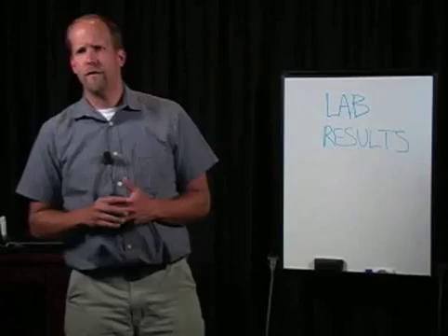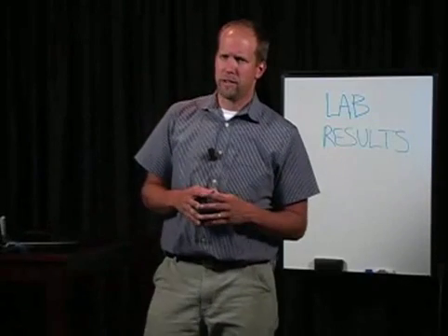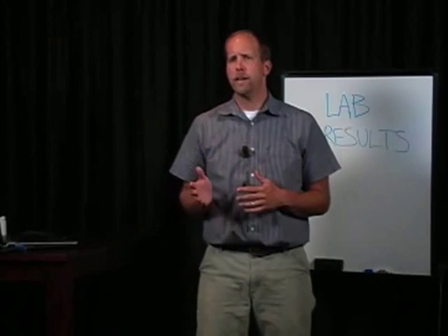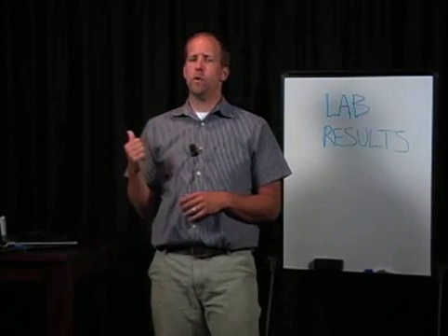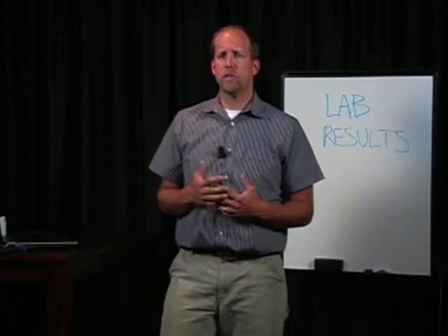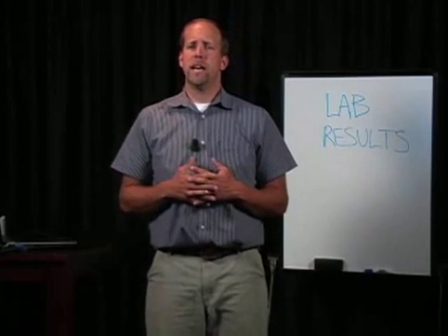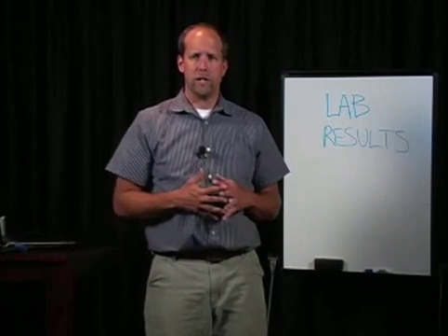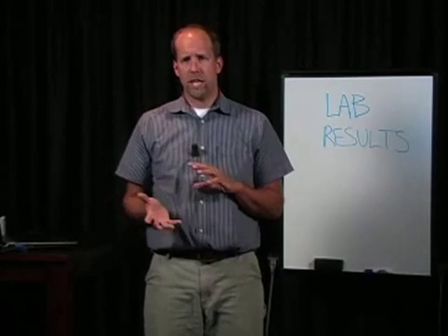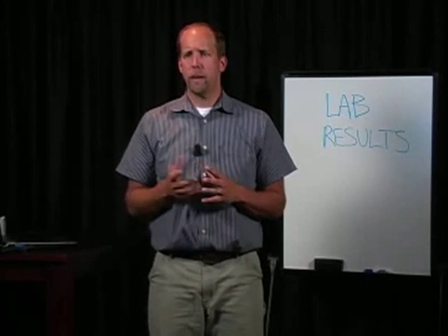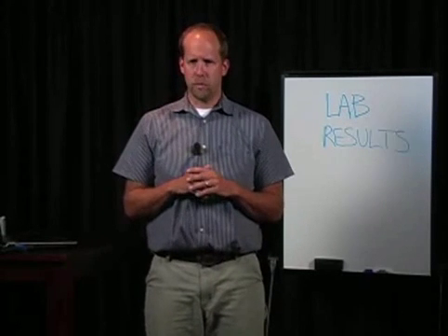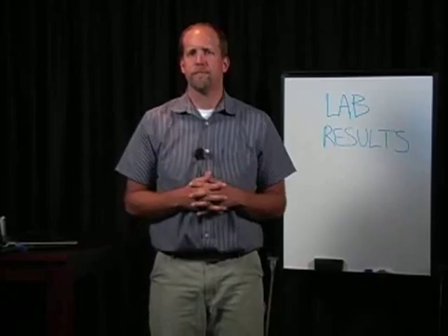HEPA vacuums, high-efficiency particulate air vacuums, are recommended for the final cleanup of remediation areas after materials have been thoroughly dried and contaminated materials have been removed. HEPA vacuums are also recommended for cleaning up dust that has settled outside the remediation area. When changing the vacuum filter, workers should wear PPE to prevent exposure to mold that has been captured in the vacuum.